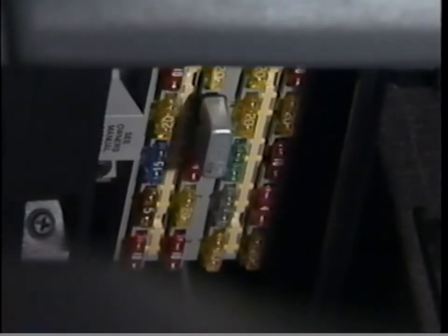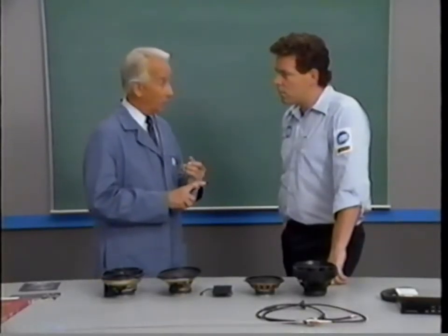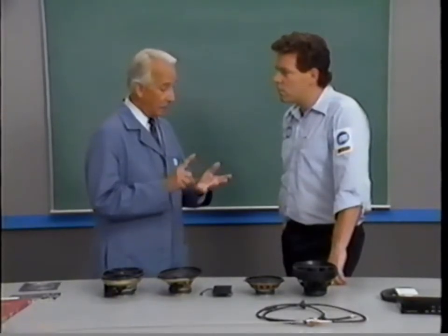Check your service manual to find out what fuses in the fuse block pertain to the radio. Most Chrysler radios contain at least 2 fuses. One ignition feed, normally labeled radio in the fuse block, and one for the radio memory keep alive feed. Because the vehicle we're working on has an RS system, we have one additional fuse, one for the trunk-mounted amplifier.